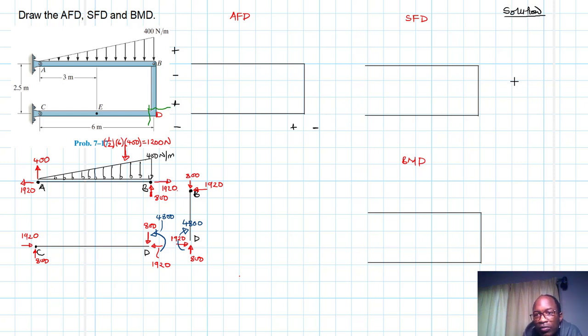The rate of change of axial force, I'll call it just A prime, is equal to Q star, and this Q star, I want to differentiate it from the lateral force on the member. Q star is the axial distributed force, and therefore the axial force itself is just the area under the axial distributed force. And then V prime is equal to the lateral distributed force, and therefore the magnitude of shear is just equal to the area under the lateral distributed force.